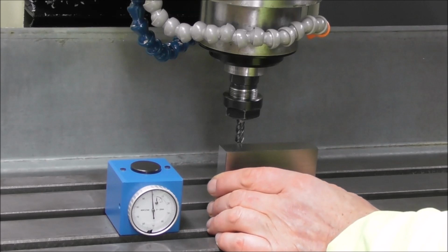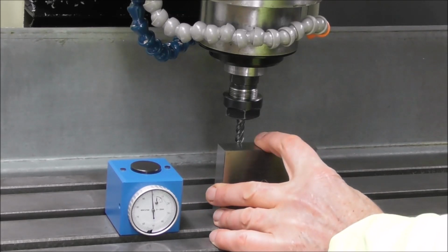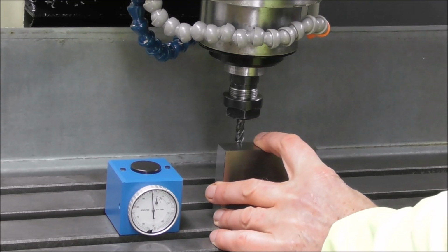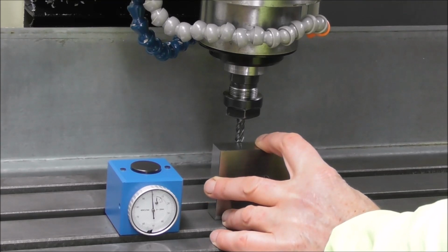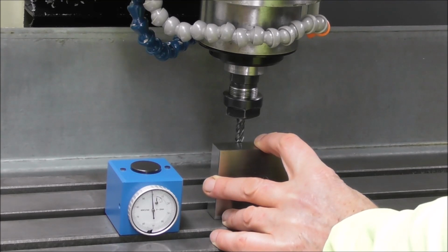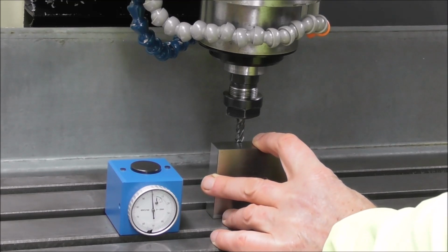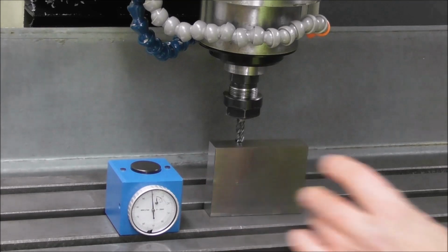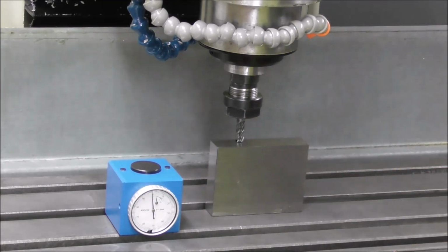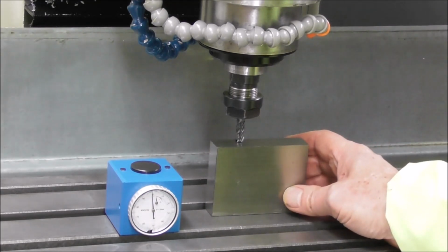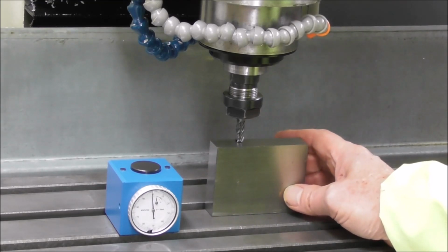So we come down now below the level of the work, push the work in and come up with the tool. And this introduces another way to set your tool offsets. So now I'm pushing in and I'm lifting the tool up with very small steps. And it just goes under at that point. And I'm 3 microns out. So tool number 6 is showing a Z height of 0 within 3 microns. That's within about 1/10 of a thou.